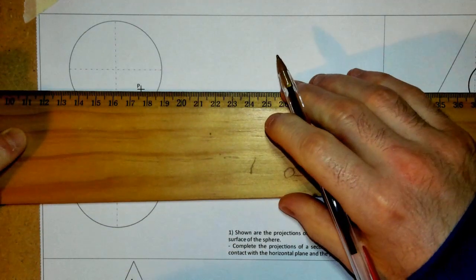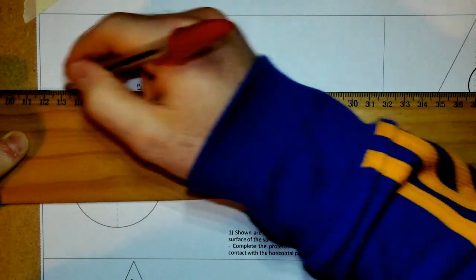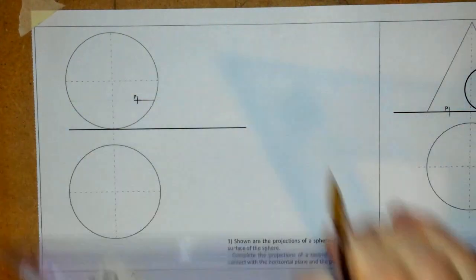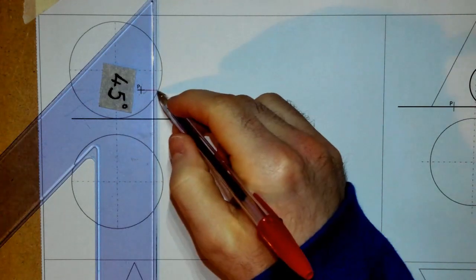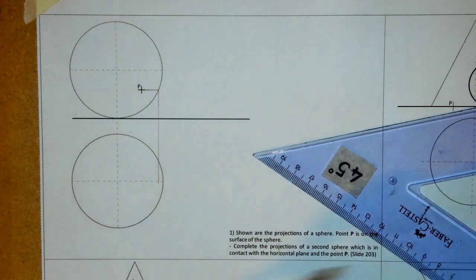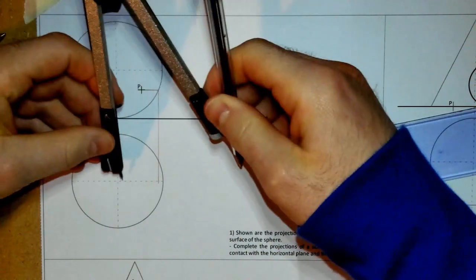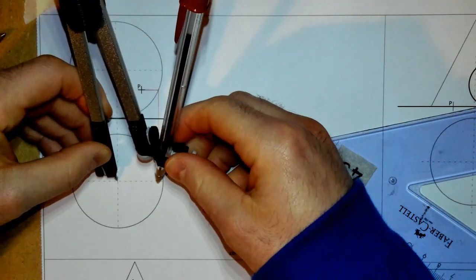When it's a sphere, I'm going to take a horizontal cutting plane, and generally the horizontal cutting plane will go like that, but we don't need to do that now. Where it hits there, I'm going to transfer it down to my plan view, and when we do a horizontal cut on a sphere, we know that the image produced by it is another circle in our plan.